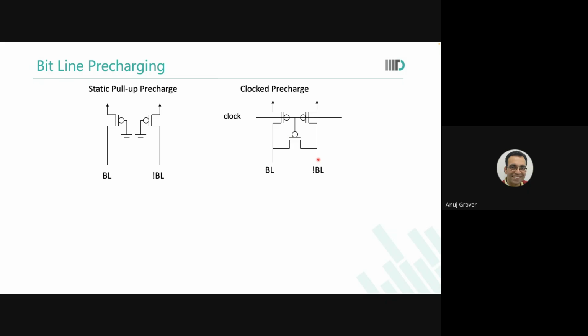So go back to the first thing we discussed in this signal flow. We said that when the clock comes, you turn the precharge off. So in the write cycle, precharge is off. It is at the end of the write cycle that precharge will turn on again. That is what I'm talking about.